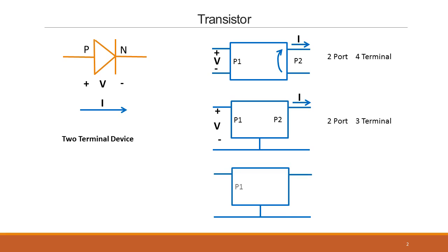Okay. In the special case where the voltage across one terminal affects the resistance across the other terminal, the control voltage here affects the resistance across these two. Where resistance means the relationship between V_O and I, the voltage across the port to the current from the port. It is a transresistor. Trans because this control voltage is affecting the value of this resistance, and it is a resistor between these two ports. So it's a transresistor, right? And that's sometimes called a transistor.